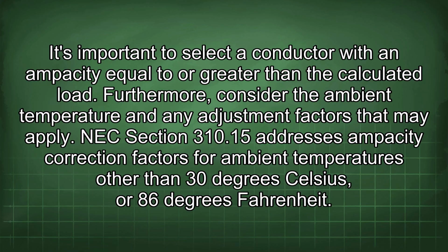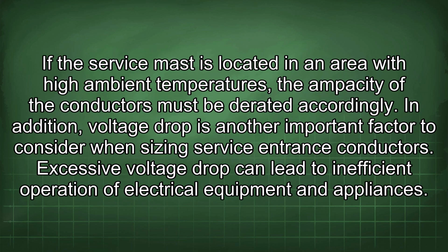Furthermore, consider the ambient temperature and any adjustment factors that may apply. NEC Section 310.15 addresses ampacity correction factors for ambient temperatures other than 30 degrees Celsius or 86 degrees Fahrenheit. If the service mast is located in an area with high ambient temperatures, the ampacity of the conductors must be derated accordingly.